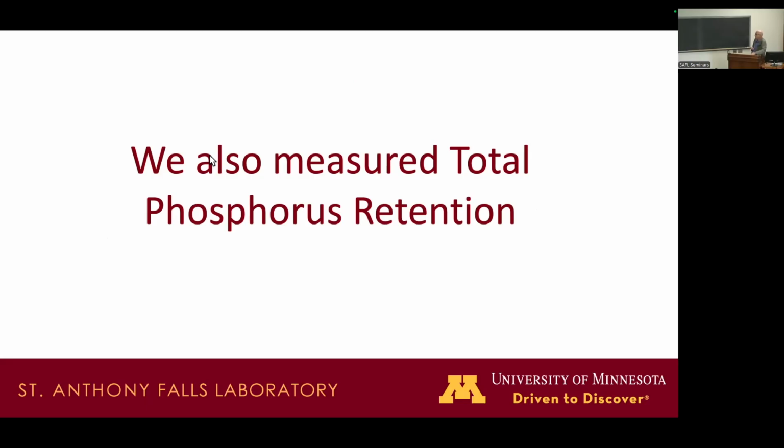Now, people are really interested in total phosphorus retention for the most part. For total phosphorus retention, a sand filter is designed to retain particulates. And we have data out there on that. There's data in the International BMP database on sand filters, how well they remove total phosphorus. But we thought we'd give this to you anyway. So here's how the iron-enhanced sand filters work with regard to total phosphorus retention.